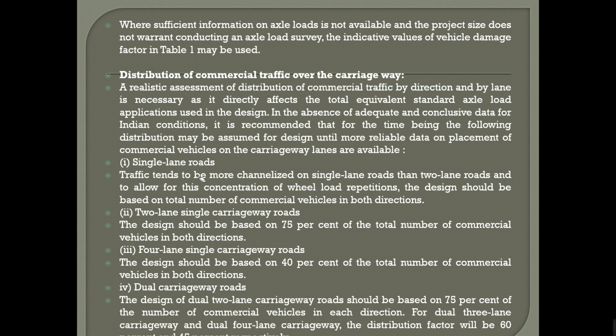For a single lane road, traffic tends to be more channelized than on two lane roads. And to allow for this concentration of wheel load repetitions, the design should be based on the total number of commercial vehicles in both the directions.